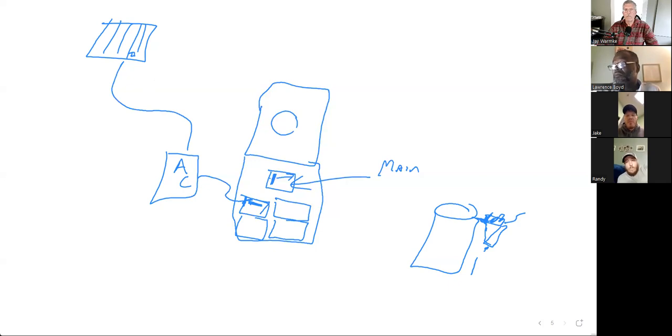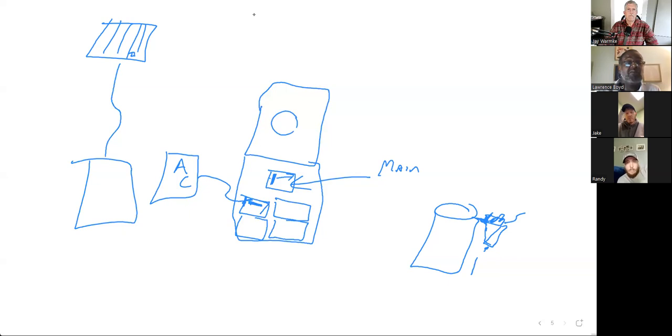And you can just work on it. So with a typical microinverter system now, with a combiner box, your system's going to look a little more like that, coming off the roof. And in this combiner box, you can typically come in with 4 20-amp breakers. So each of these breakers is going to be 20 amps. So I could come in with 80 amps total.